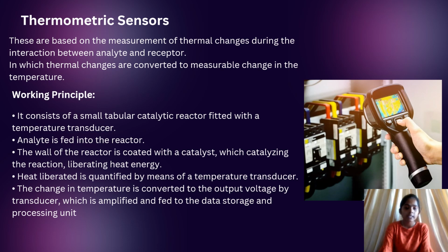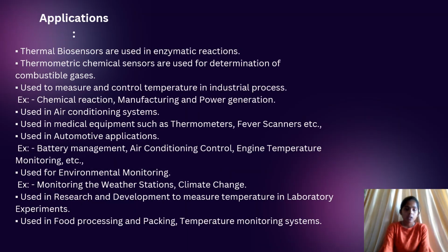The wall of the reactor is coated with a catalyst which catalyzes the reaction, liberating heat energy. The heat liberated is quantified by means of the temperature transducer. The change in temperature is converted to an output voltage by the transducer, which is amplified and fed to the data storage and processing unit. Applications of thermometric sensors: thermal biosensors are used for enzymatic reactions.